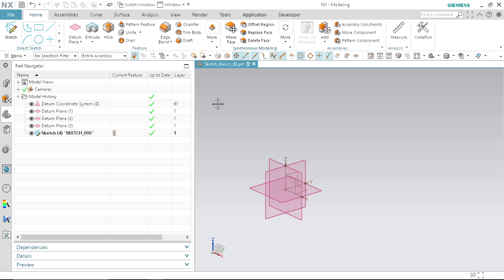In the drawing there are multiple curves which have the same dimensions or something similar. You can reduce the number of dimensions in the sketch, and if you have to make a change, with fewer dimensions you can change within minimal time. So that's why we use geometric constraint in the sketch along with dimensions.